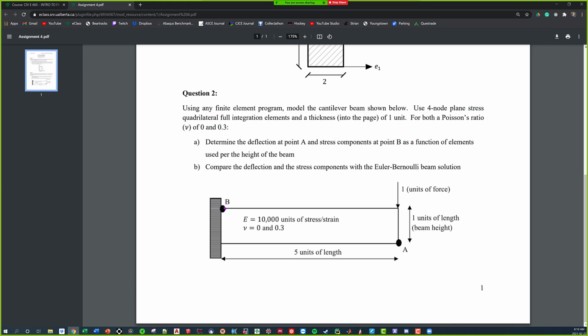So every time you guys increase your mesh size, as you guys see, the stress kept going up. And that's what it's doing. It is converging, but it's converging to infinity. So you guys will actually never see the end of it. And there's been a lot of research done trying to figure out nice relationships or the theory based on that convergence. So hopefully that makes a little bit more sense to you guys.